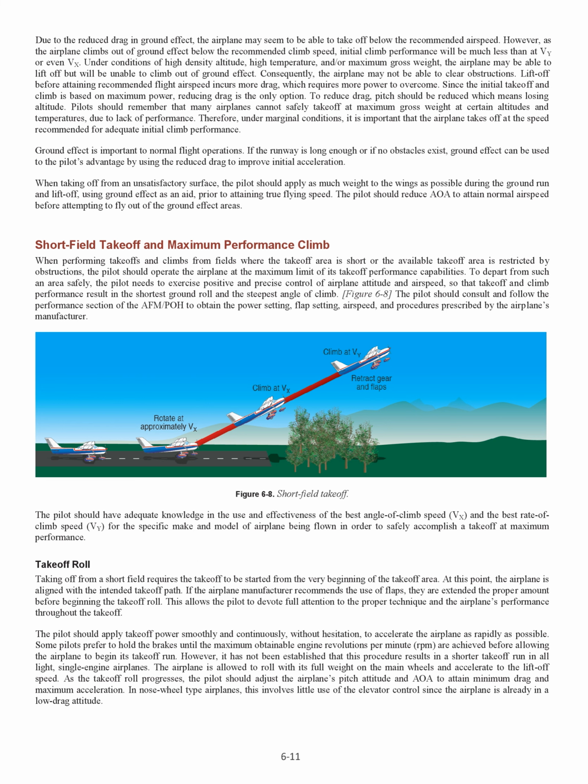As the takeoff roll progresses, the pilot should adjust the airplane's pitch attitude and AOA to attain minimum drag and maximum acceleration. In nose-wheel-type airplanes, this involves little use of the elevator control since the airplane is already in a low drag attitude.